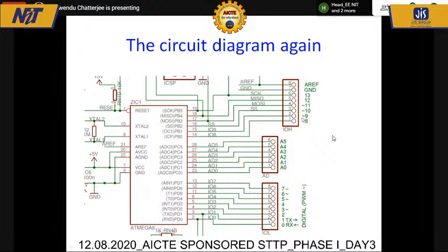And this can also act as PWM control. This sign tells you on the board. They have their own sign. This is not the microcontroller sign, this is the board sign. So along with pin number 9, pins 10 and 11 can also give you PWM output if I change the register. At present, we are only working with pin number 9.